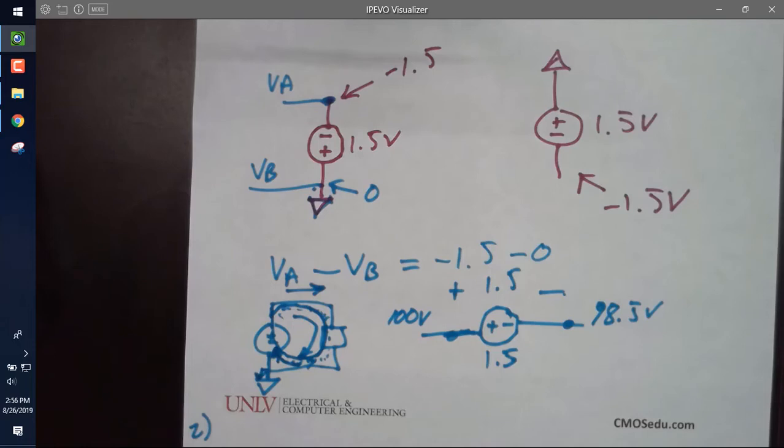And in fact, in your house or apartment, what do you call the circuit whose job in life is to ensure there's no current on the ground? When you plug your hair dryer in, if you have hair, unlike me, what do you call that circuit? It's got test, reset, GFI, ground fault interrupter, ground fault circuit interrupter.